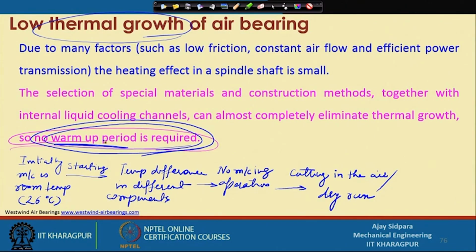So, that is a very big advantage here: it has low thermal growth. So, you do not need to give a warm-up period. As soon as you start the machine, within a few minutes you can start doing operations also.